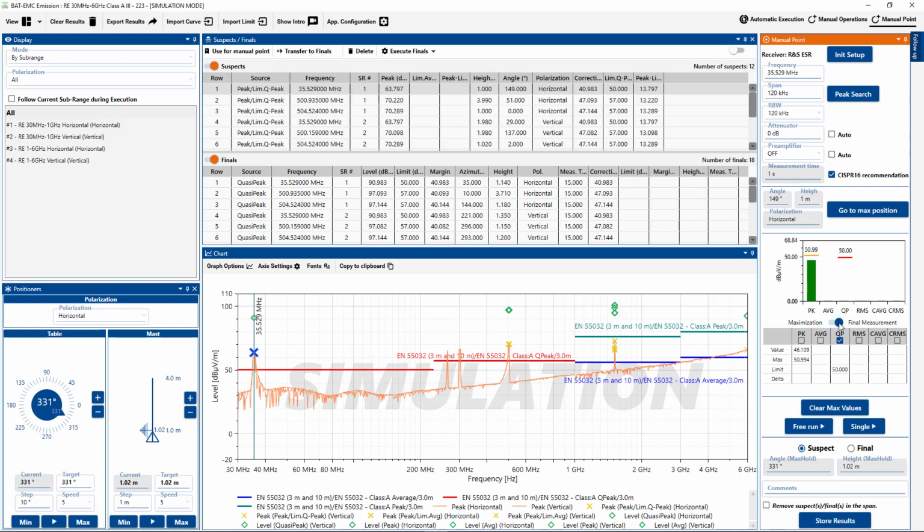Because we're in a range below 1 gigahertz, we're going to use the quasi-peak detector for that. And as you can see, because I changed to the quasi-peak detector, the measurement time came up to 1 second. It could be set to a higher amount, for example, if the peak was unsteady. And then I can say to do a single run, because that will measure it. It will do a continuous measurement and max hold, and will record that value as the final value after the measurement time expires. The previous measurement and free run would not stop until commanded to do so.